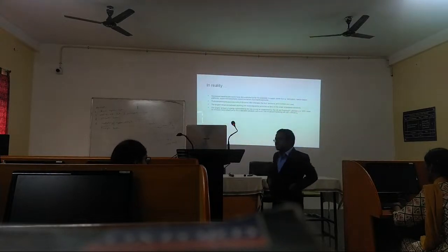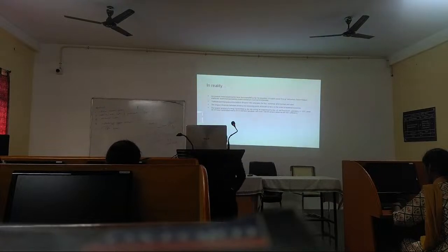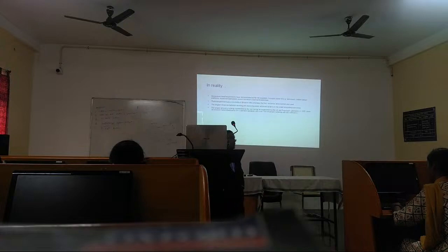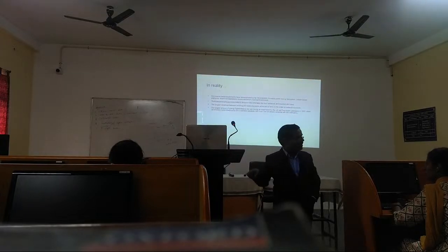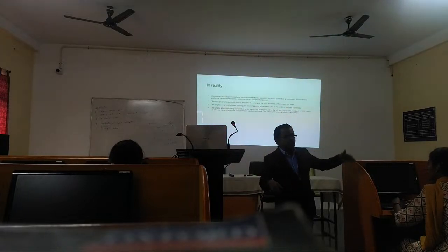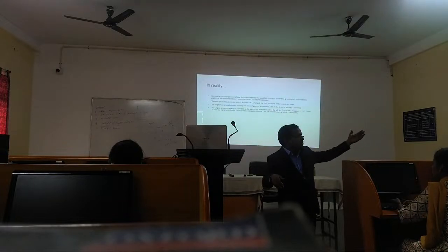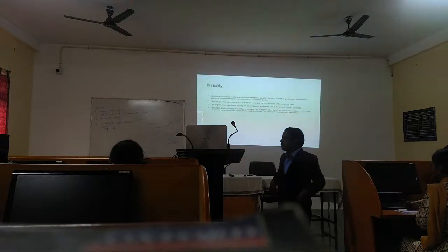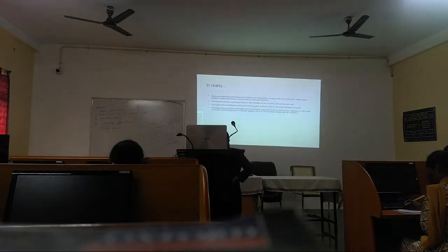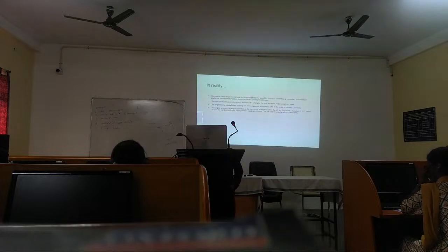As of now, the tested antenna was a 26 meter diameter parabolic dish antenna. 26 meters means you can assume this room has maybe 10 meters or 40 meters width, so twice this room, one hall and another hall. So that much diameter, a 26 meter diameter antenna, has been used. The distance was 1.52 kilometers, with an antenna efficiency of 85%.